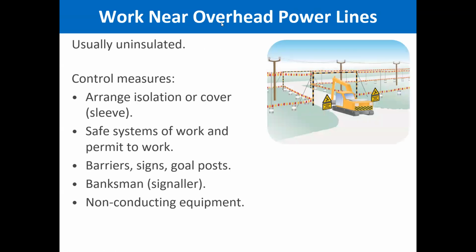Working near overhead power lines is also a very, very dangerous activity. So you need to make sure that you take all the precautions, because overhead lines almost always are uninsulated. So you will never see any insulation over overhead power lines.